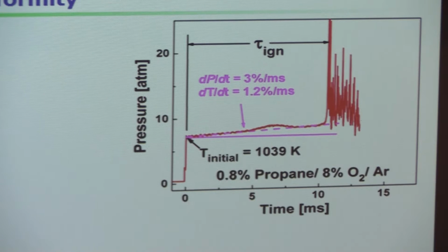And we've tracked that down to be associated with the gradual attenuation of the incident shock wave. Because the incident shock wave is slowing down, the post-shock pressure P5 gradually goes up with time. And we can account for that with some theory, but we don't like it. Because if the pressure is changing with time, and then we get the ignition delay over here, when we watch, there's the observed pressure, there's a contact surface bump. That means we did not do the tailoring perfectly. We did it well, but we didn't do it perfectly. If we'd done it perfectly, this would have been a straight line. And now it goes bang. So that's the ignition delay time we observed in this experiment.